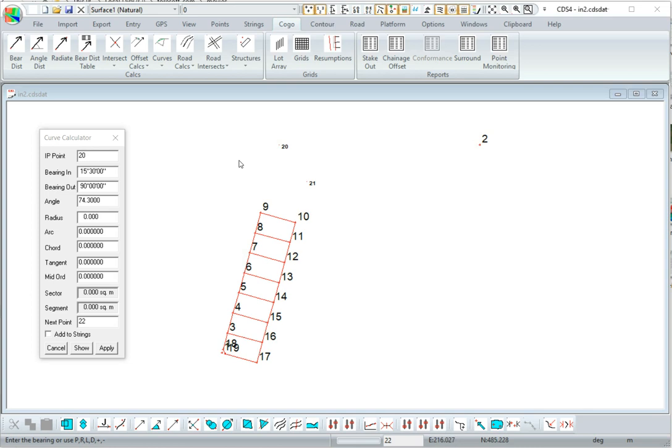In this example, we want a tangent length of 12 meters. If you do the calcs, you get a radius of 15.7. So here we're going to use a radius of 15. This is described a bit more in the online manual, so maybe read the online manual while watching this video as well. Press tab, and that gives us the arc distance and a tangent distance and what the area and things is. And I think we will accept that.